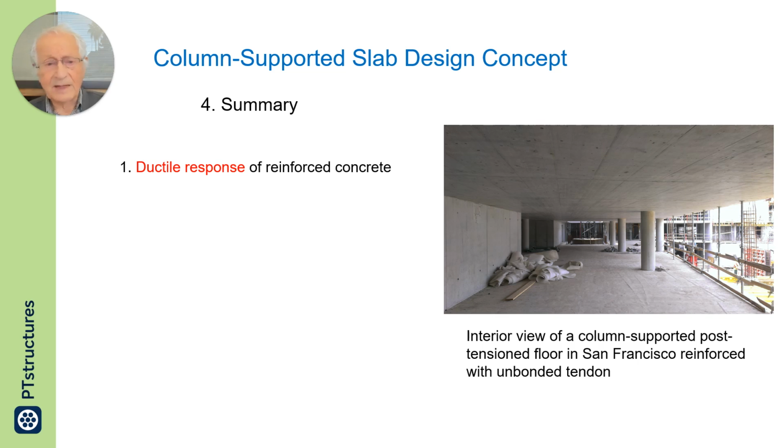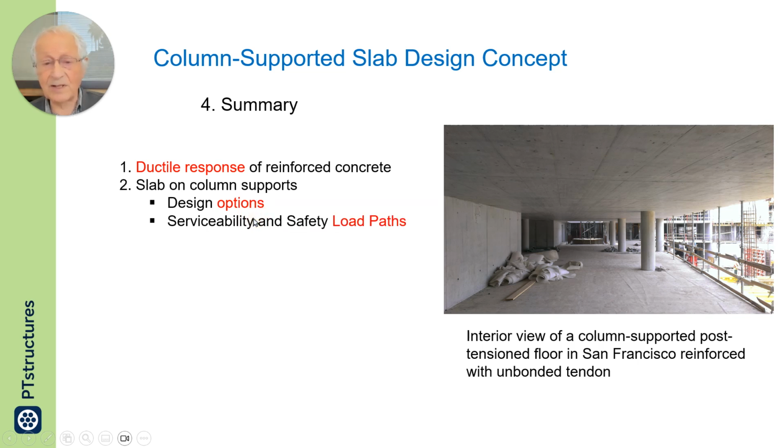And I started by emphasizing the ductile response leading to redistribution of demand to where resistance is available. Focus was on slab on column supports. I talked about design options, serviceability and safety. I want to repeat myself. For serviceability, you have one load path. For safety, you have multiple load paths.